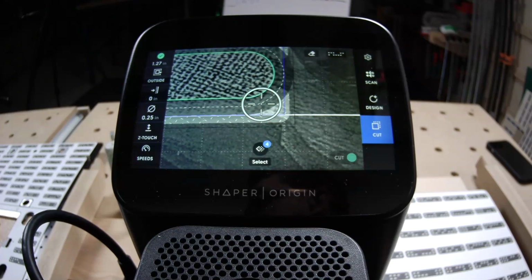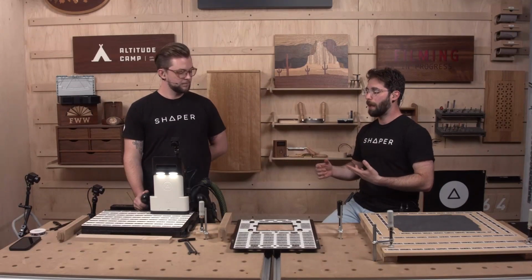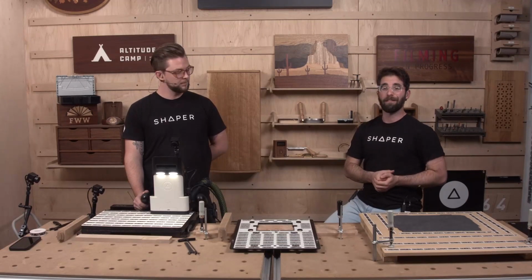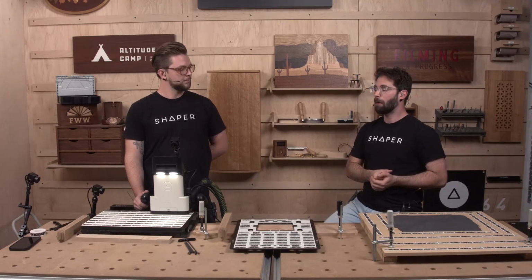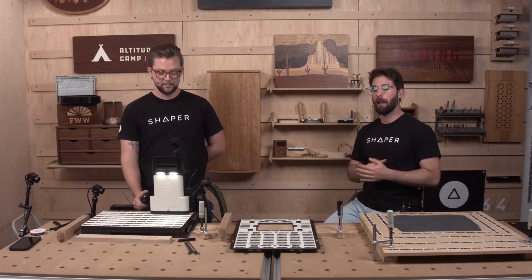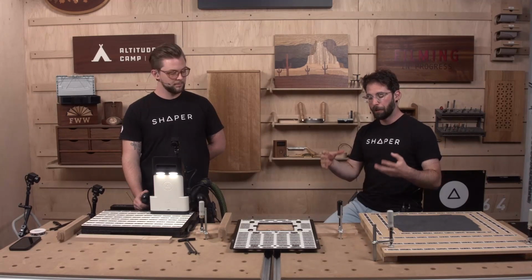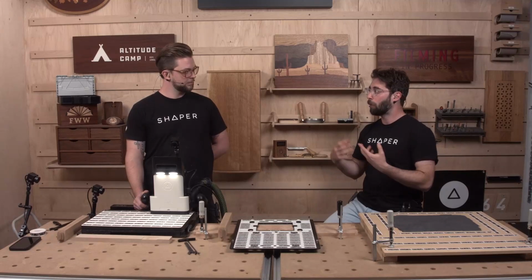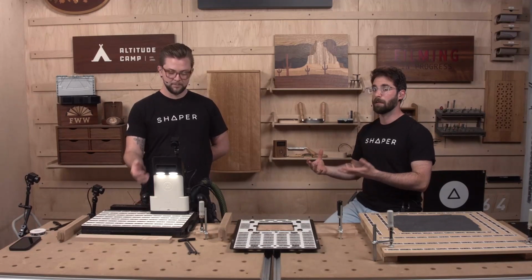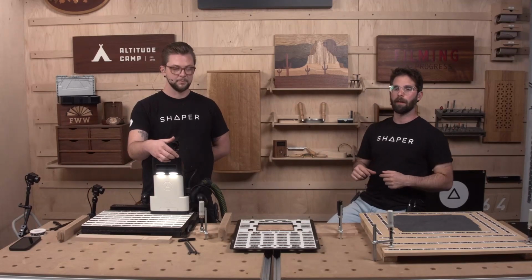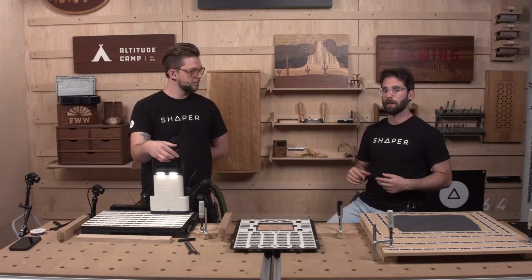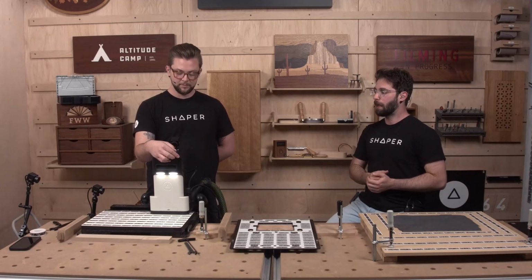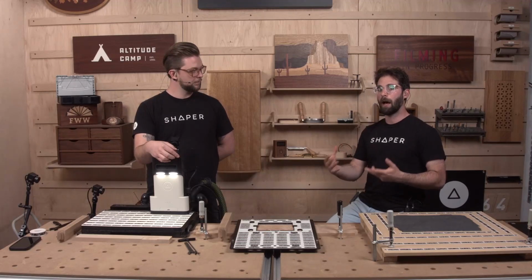Where that could be annoying, though, is what if I have a file that's designed for 1/2 inch thick plywood and I want to cut it out of 3/4 inch plywood. Basically, every time I cut through that plywood to full depth, there would be a warning that says, hey, you're going to 0.75 rather than 0.5 inches that the file's designed for. That's why we put that override or that hide warnings there.